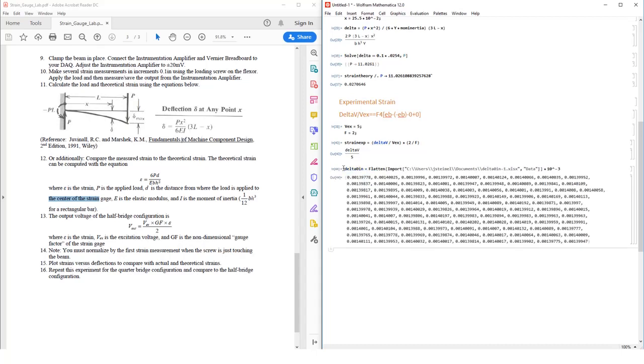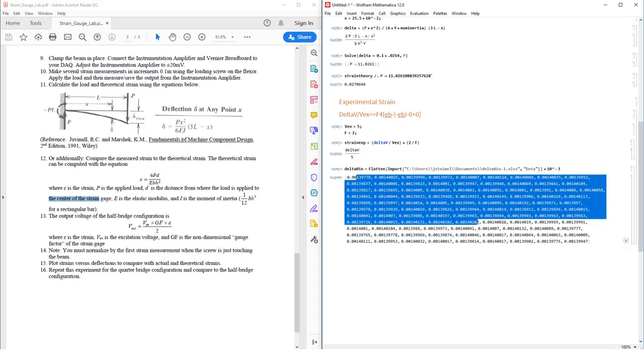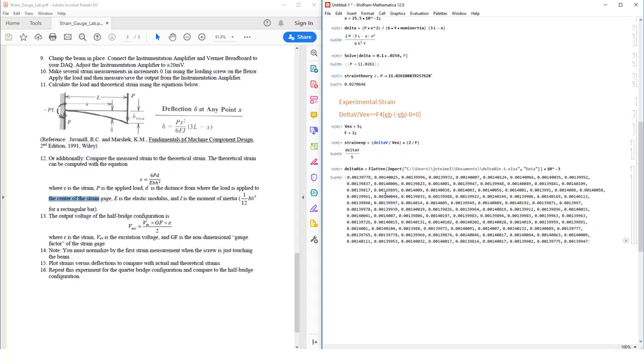I measured this, obviously, again, we're taking it with the DAQs, making multiple measurements as a function of time, but this is your resultant voltage. Now, you might be asking, how are you measuring a voltage when you didn't apply any deflection? Well, when you first apply the strain gauge, you have to press really, really hard in order to make it stick. So often you'll read some resultant voltage from pre-straining that strain gauge.